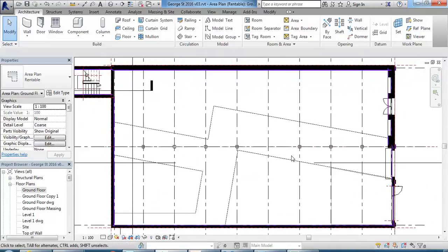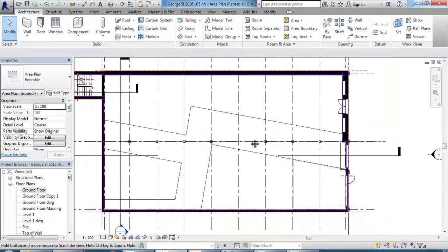And actually, do you know the difference between floor space and floor area or rentable area? So floor space in most cases is measured to the outside of the wall, and rentable area is measured, well, in different ways, but at first you can probably just do it from the centre of the wall. You find that real estate agents have their own way of doing it, where they measure partly into the wall to work out what area they're going to charge you for. But when you're working out the rentable area, just focus on the interior at first.